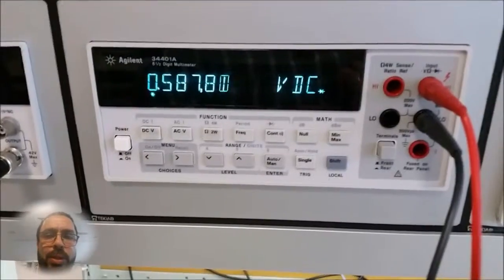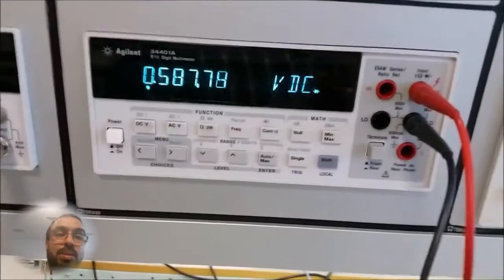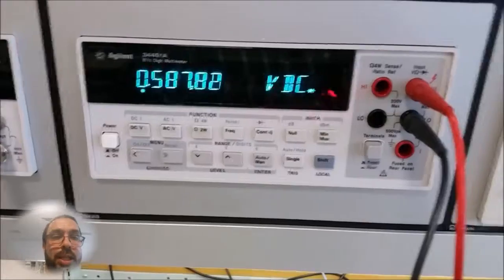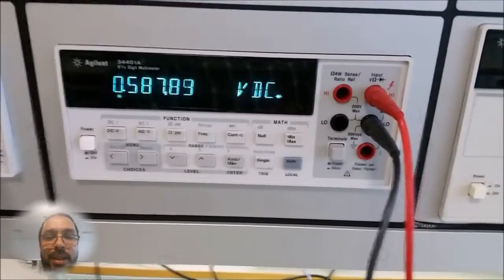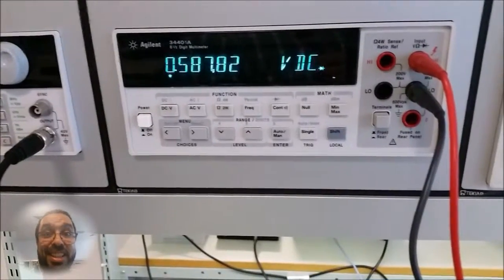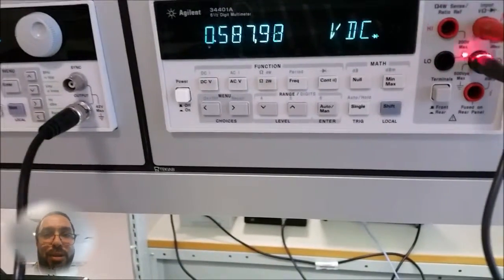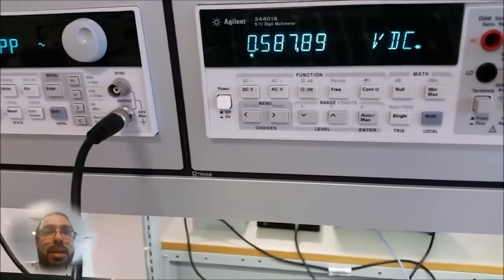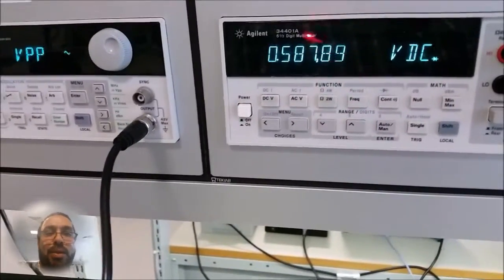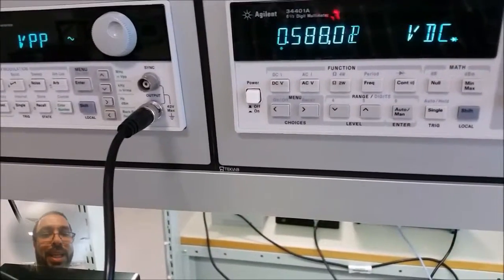So, which one to trust? What we need to trust now is our circuit. So what is this value really giving us? Actually this port is measuring the barrier voltage at 1 milliamp. Because the diode starts to conduct, but then it will reach 1 milliamp after a certain voltage, and that's the voltage that you see here. So yes, this is the built-in or barrier voltage, but at 1 milliamp.